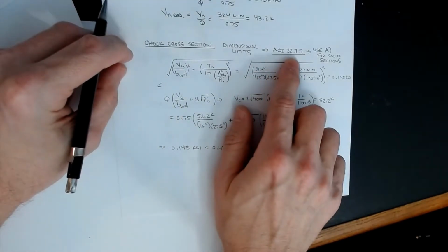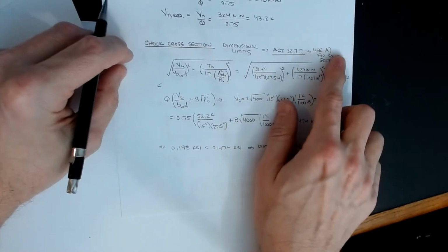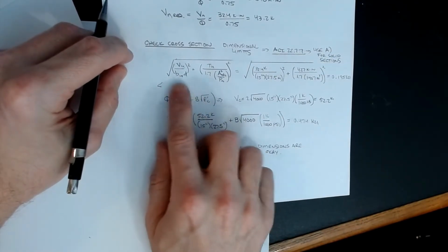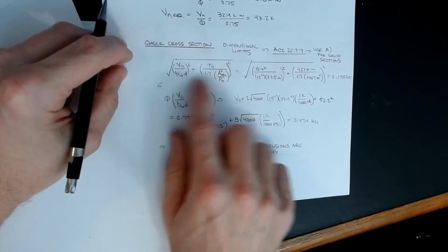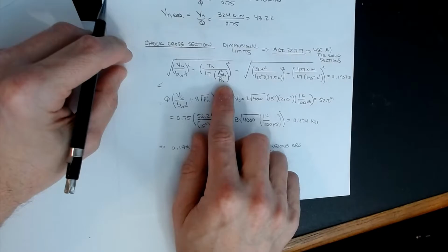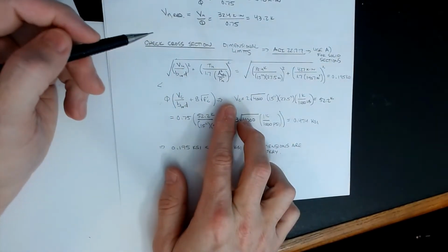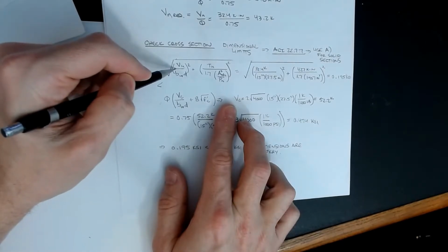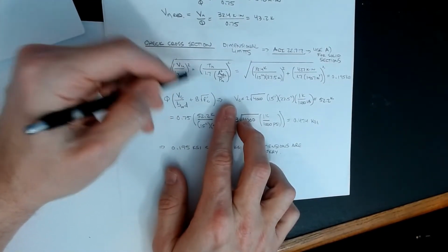This is in 22.7.7. Okay, we have a solid section, so we use the first formula. And this is where I caught the error in my notes before, because I had left off the squared on these when I did it. So this is where the correction came in. All right, so that formula that we corrected now looks like this. Okay, and so we have an average shear stress from the direct shear, and then I have the shear stress that's coming from the torque coming in here.